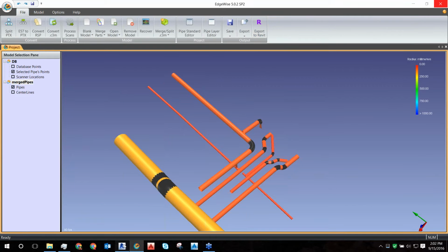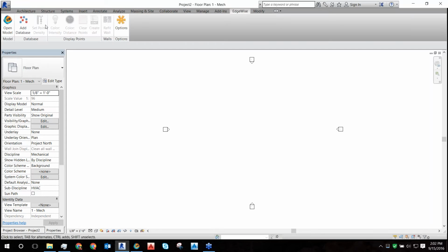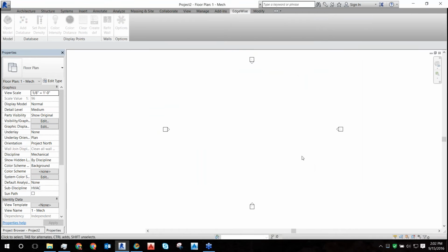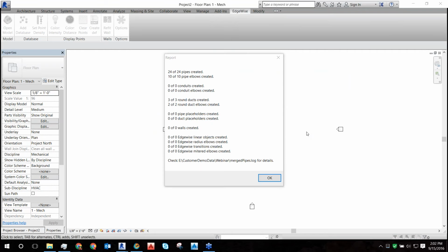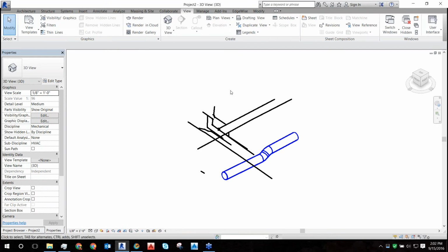Let me jump in on that a little bit. If you use survey control or hard targeting, in other words, if you have some well-defined, well-surveyed control points, you can extend the scan in the same way that you would extend a terrestrial laser scan. The trade-off comes if the geometry is very dense and congested, like inside a semiconductor fabrication facility, for example, then that effort may be justified. If it's an open parking garage, it might make much more sense to use a terrestrial laser scanner.